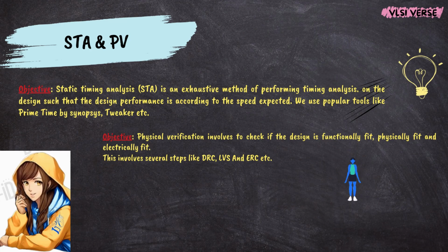This step involves checking the design against timing constraints to ensure that all paths meet the required timing. If there are any violations, the design is optimized, possibly by adjusting placement or resizing cells to achieve timing closure. This is crucial for ensuring the chip operates correctly at the target clock frequency.